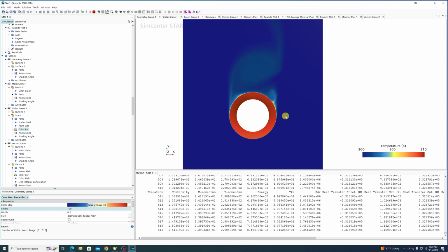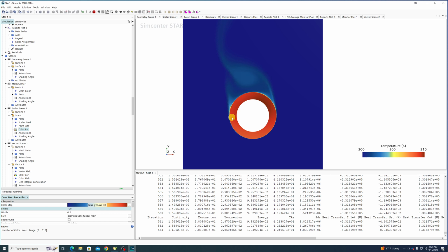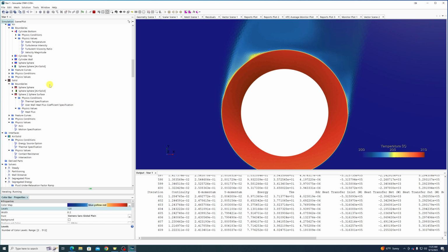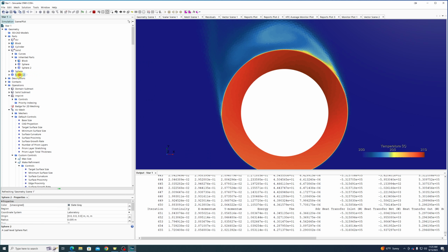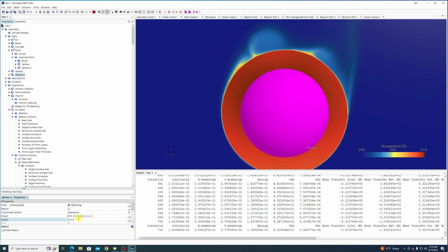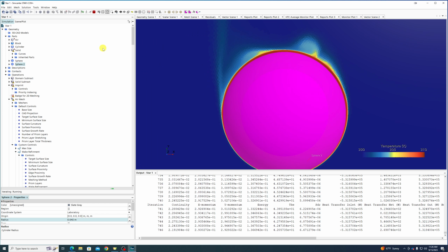So you can either have a solid body, or you can have a relatively thin body that's just a wall thickness. Just don't make this wall thickness too thin, because if you do, you're not going to have enough cells in that boundary. Like, for example, here, I could make this very, very close. Let's say, oh, I'm probably going to regret this.